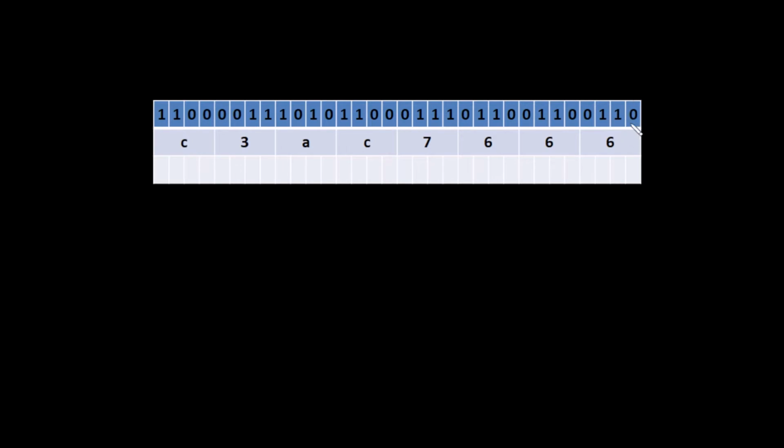This end here is the least significant bit, and this end here is the most significant bit. Now we don't want to put these 32 ones and zeros into our adder and subtractor. It's much simpler if we only have to put in 8 bits. And these are the 8 bits of the hexadecimal value which represent this 32-bit number here.